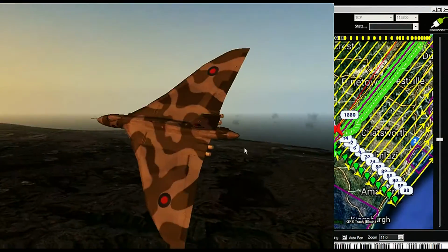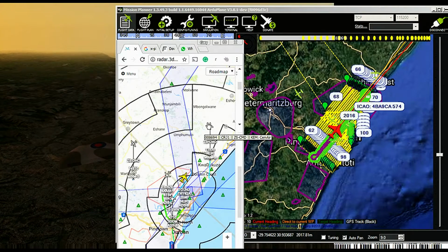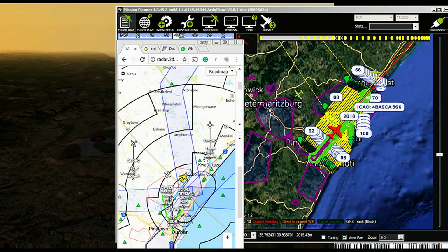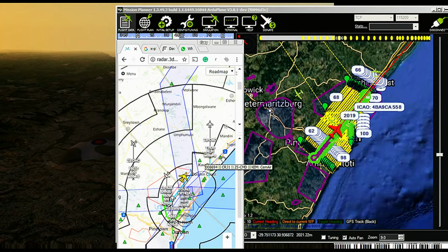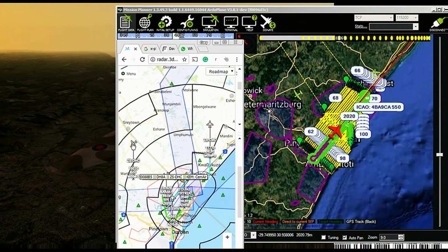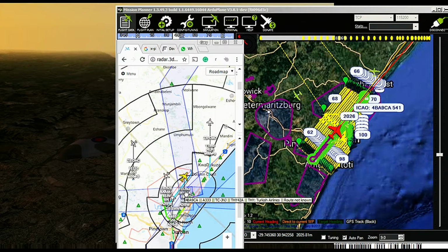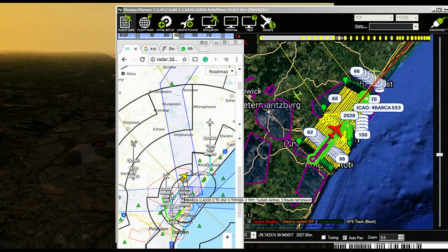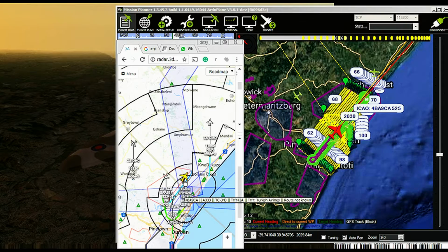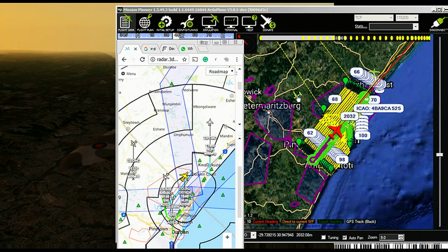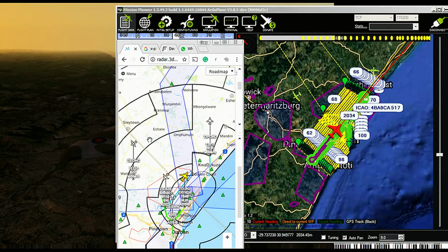There is a problem if you just use ADS-B, and that problem is you won't see another sort of transmitted traffic. That's Mode S traffic, or well, you'll hear it, but you won't get its position. You need multiple receivers in order to get a position for it, and then compute it and put that back into the system. So that's why just having a receiver on board your drone is not good enough in and of itself. So where can we take this next?